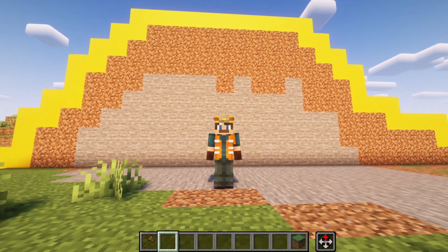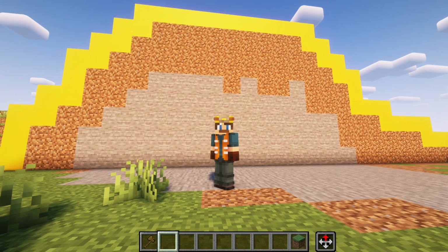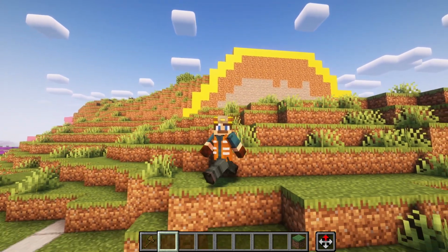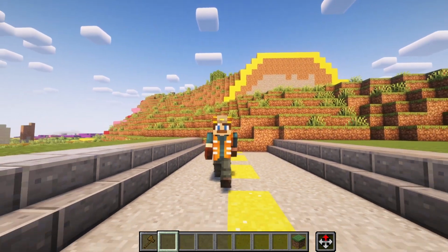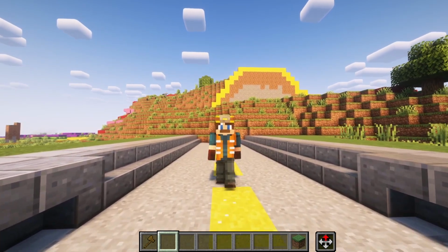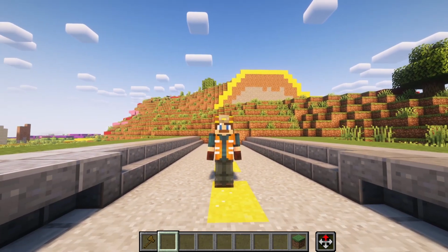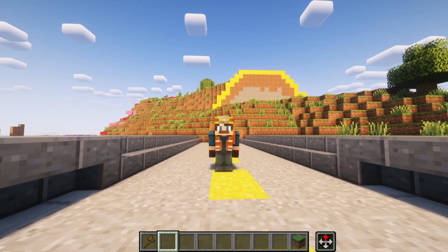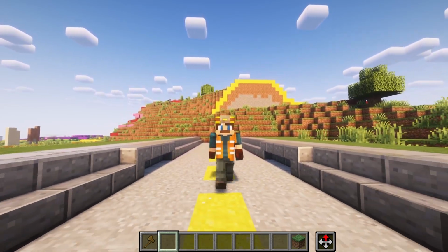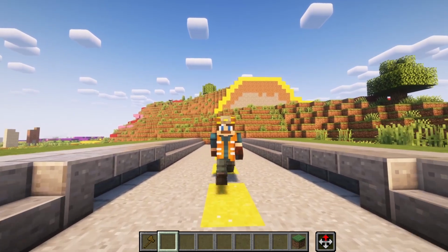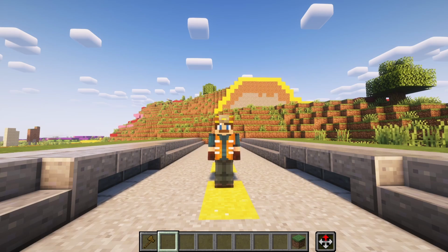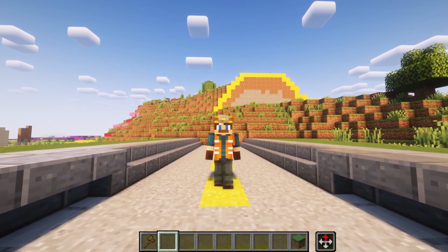Often when designing things in engineering, there are some key factors when it comes to stormwater quality. We're often designing builds to withstand the 1, 2, 5, 10, and even the 100-year storm event. And just as it suggests, the 1-year storm event is pretty minimal. The 2-year, the 5-year, the 10-year is where we start getting into the realm of needing to develop the proper facility management of that water. And then the 100-year event is the largest storm event, which is often on a natural disaster level. We want to make sure that all of our stormwater facilities, our ponds, our networks can withstand the volume of water and the time that it falls.